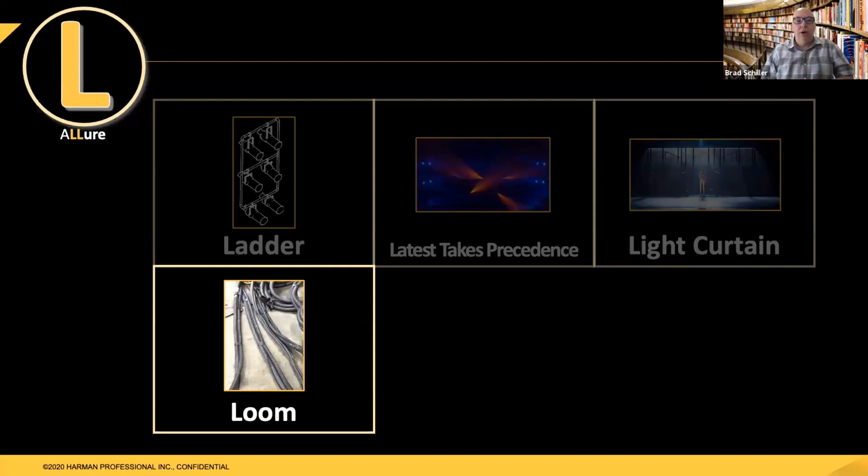For tours, quite often, a loom will include power and data and other cables all running from a distro location, tied together. It goes up to the truss and then out and along the truss, breaking out to its various positions as needed. And looms are very useful because it keeps those cables bundled together nicely and also allows ease of setup and teardown of those multiple cables.